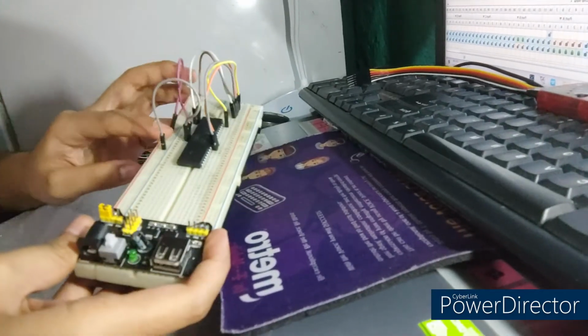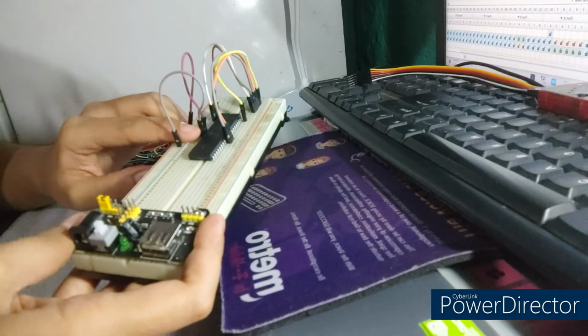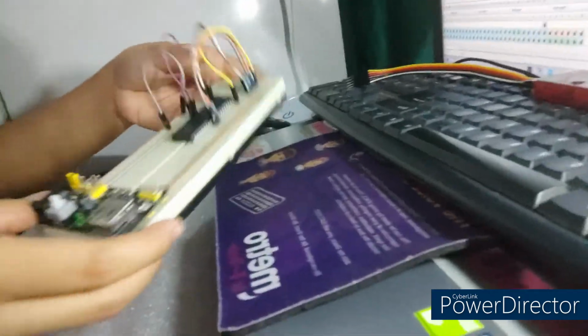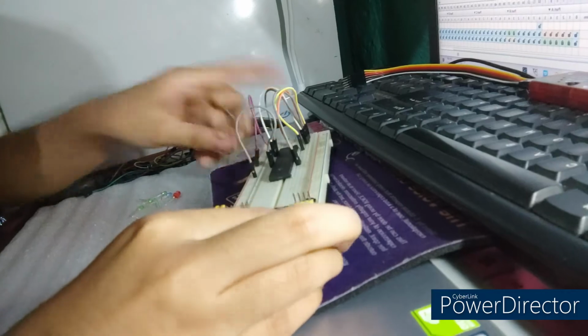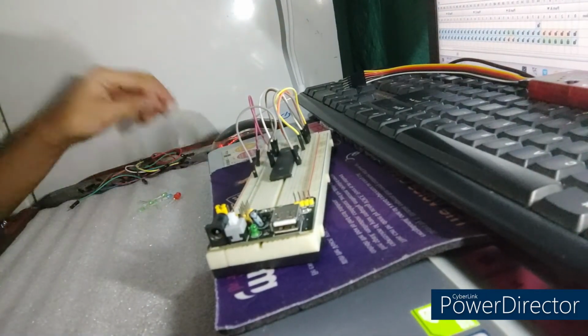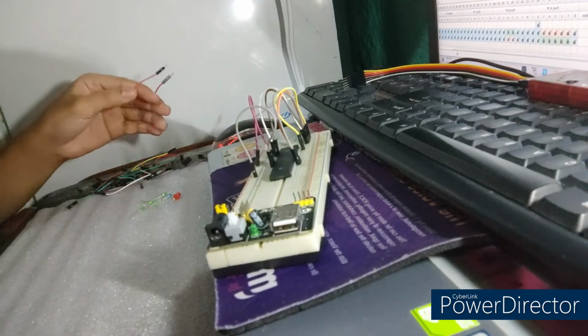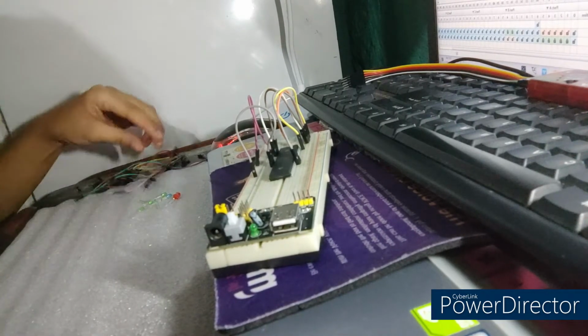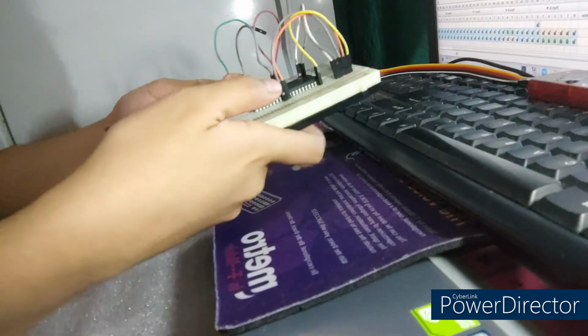So again, the IC is already connected to the VDD and to the VSS, where VSS should be connected to the ground, and then VDD to the positive voltage supply. And then we will be needing our LEDs, 6 LEDs. So for our first connection, we will be connecting RE1 to RE5 of our IC to our LEDs. So let's have some connection. So RE1 is on pin number 3 of the IC.